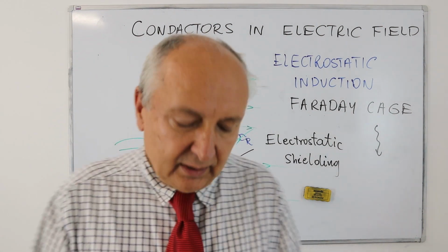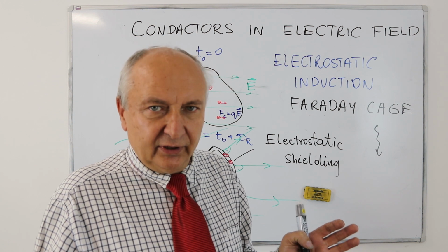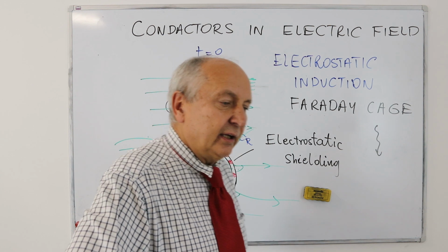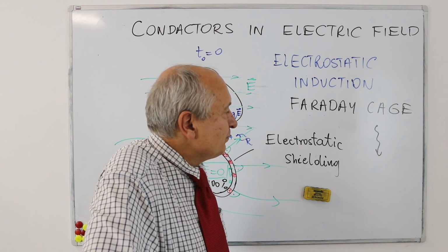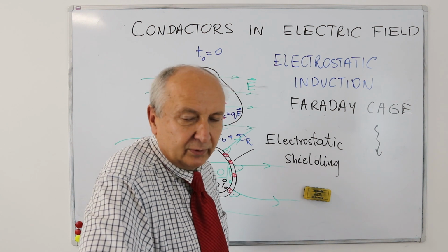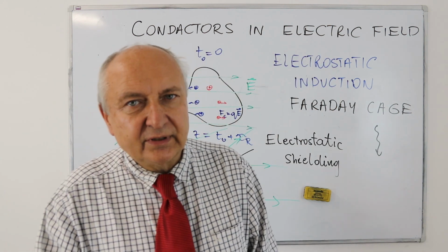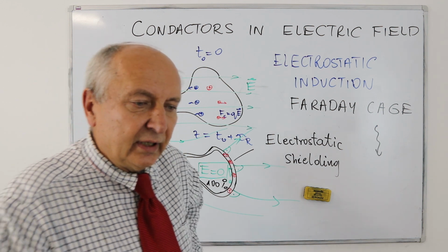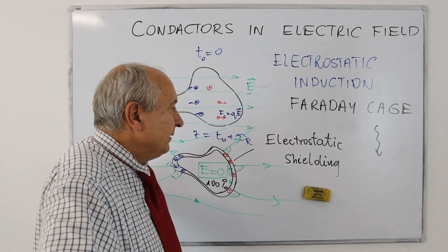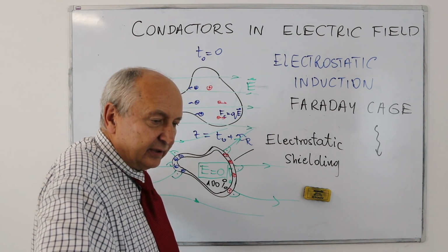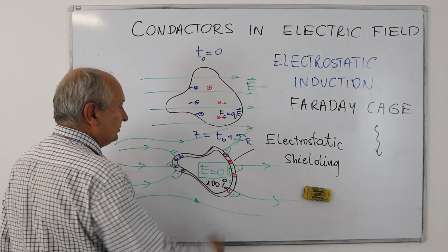And they measure as well, because the ambient is empty of electric field. You don't have any electric field inside. They can measure what is the noise produced by electric equipment, and they do such research for firms that produce electric equipment, because the norm tells us what level of noise is allowed for every kind of electric device. So the Faraday cage is a very useful tool for research of electromagnetic compatibility.